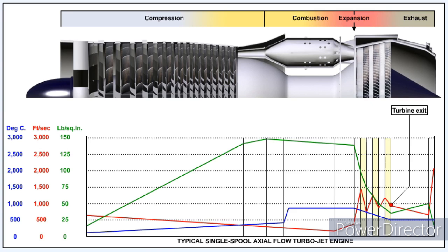The velocity of the gas as it leaves the turbine can be between 750 and 1,250 feet per second. This is somewhere around 0.5 Mach. If this gas has to negotiate a long jet pipe before being ejected into the atmosphere to provide thrust, a great deal of turbulence will be caused within the pipe. This will lower the efficiency of the engine and reduce its thrust.